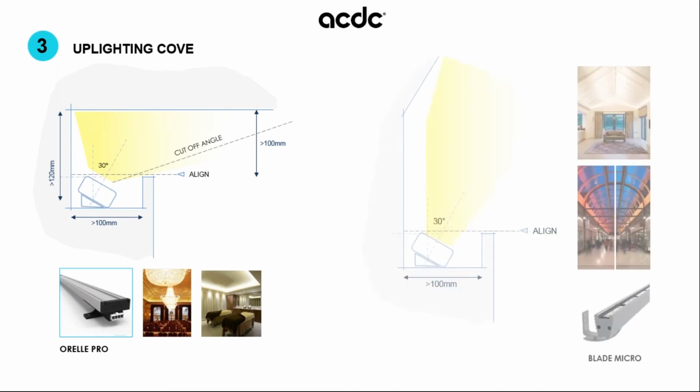Another way of uplighting, where maybe you're not restricted, is to use a cove luminaire which has an optic. So we're kicking out and we're grazing up that ceiling. A 30-degree tilt again, or maybe less than that, you just need to focus it. So we're grazing light up, and here again, maybe it's about single color, maybe it's about dynamic. And it's not just about color when we're talking about dynamic light. Maybe it's about dynamic white as well. So bring in that dynamic white so that we can change from daytime to nighttime scenes as well.